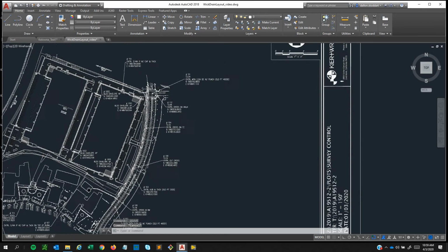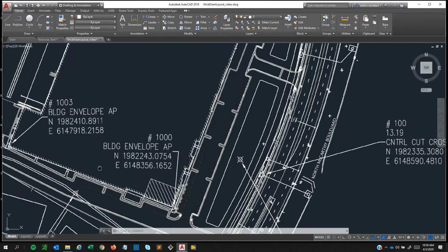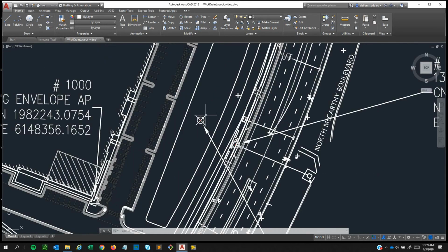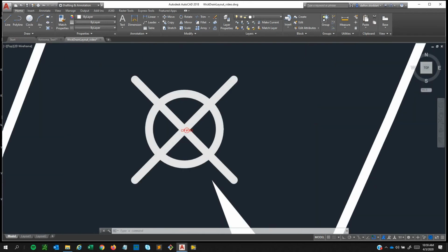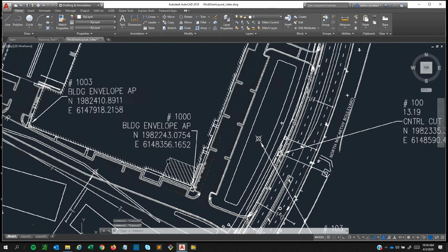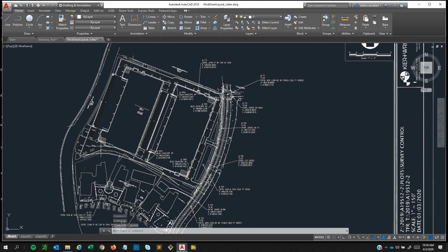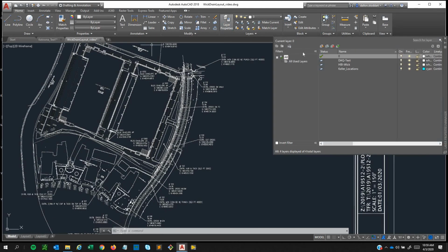The next thing we're going to do is find our layout boundary. So our building layout, I'll just check this 103. Yeah, it could be a little shifted, but it'll be good for this tutorial. So this is our building layout. We have two buildings here. In order to do a perimeter, we're going to create a new layer, and we'll call it wick drain boundary.